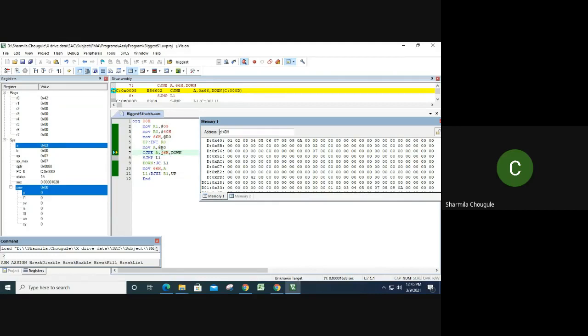Again it will compare the accumulator value with 66H. Earlier the value in 66H was 02. It will compare with the accumulator value 03 now. Again the accumulator value is greater than the memory location value at 66H, hence the carry flag will not be generated. Again it will decrement your R1 and then go to the label up. That means again it will increment your register R0. In this way it will go on doing the process till your counter R1 becomes equal to 0.